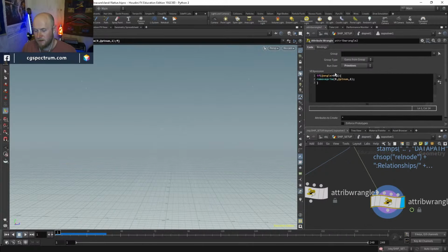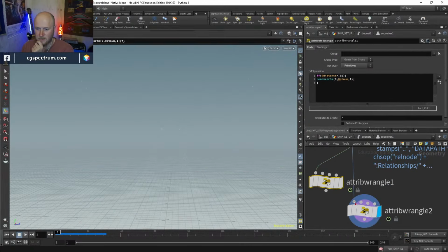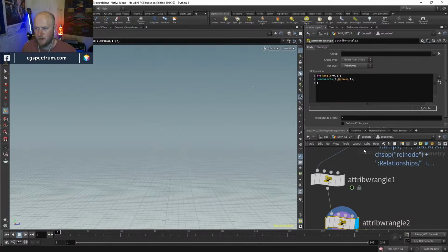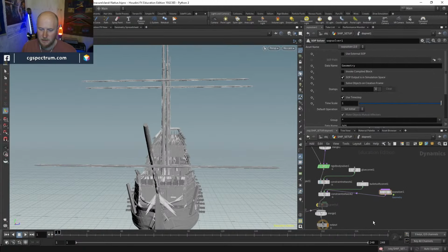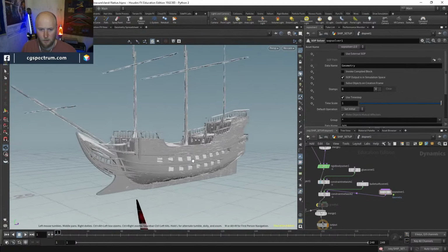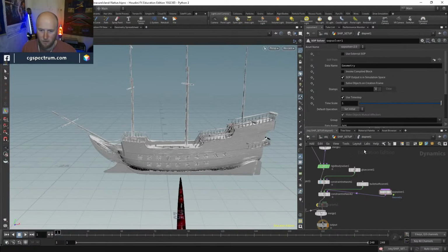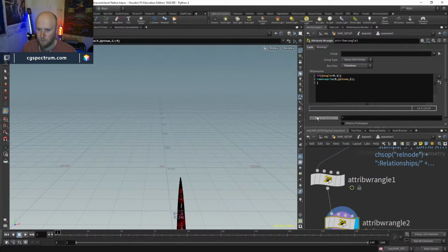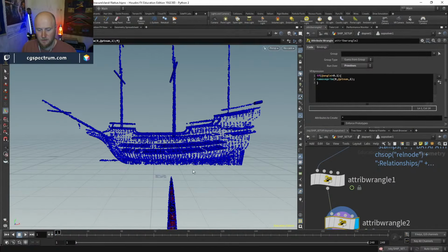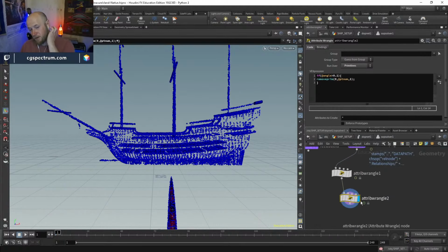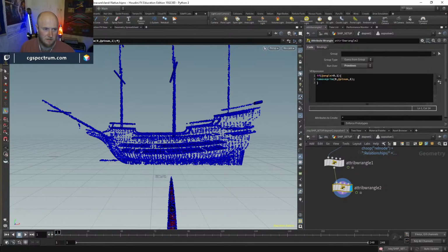You could also do both. You can layer these up so that the distance can be greater than, I don't know, 0.1 and it will break, and then you could do the angle greater than, let's do greater than 0.1. So you can just keep layering up those conditions to get exactly what you want to occur. The other thing you could do is completely remove points in the center. So you could do it in here, or you could do it out when you created them, but you might want to keep them for a certain amount of time. But I could actually blast based on a group.